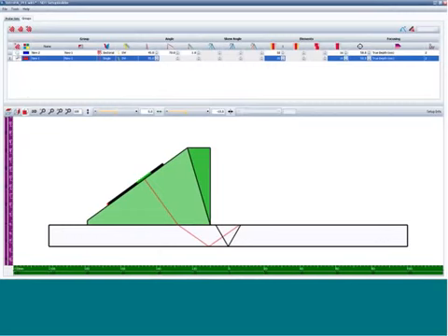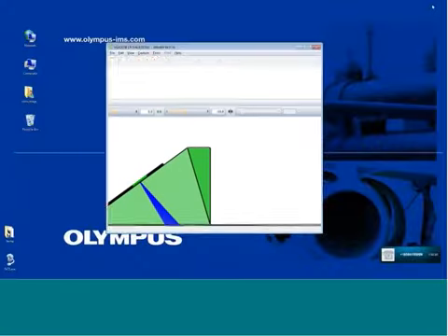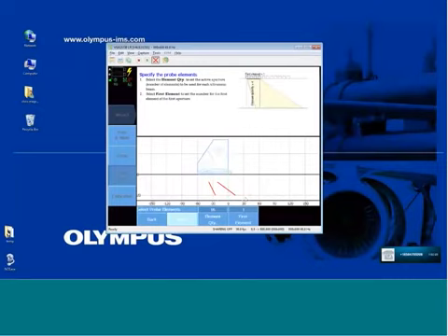and here we will see the full sector scan. 16 element aperture, or simulating a 10 millimeter conventional probe, starting on element 32. So select probe first element and element quantity.